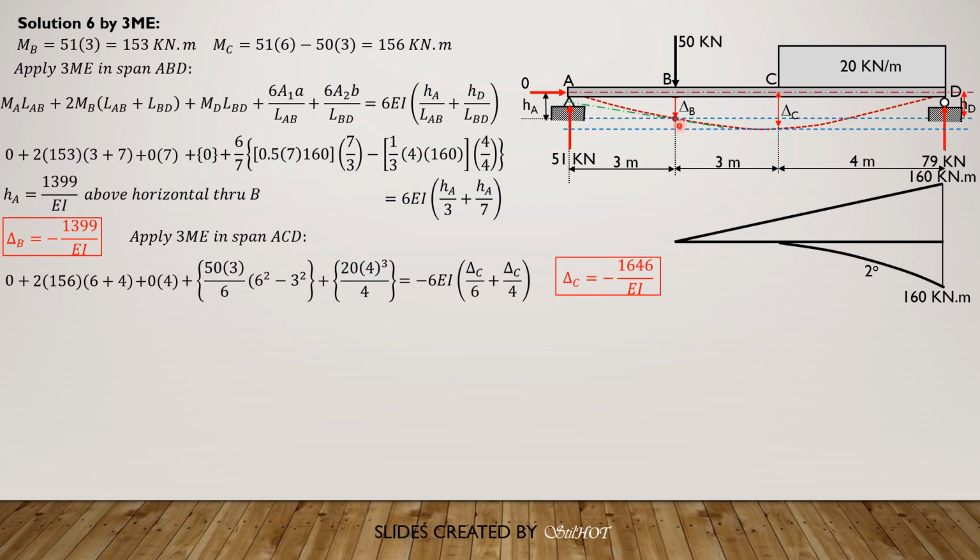Then if that is the case, the distance of point A from this reference tangent is the deviation of A relative to the tangent at B. And because this is the tangent at B, the angle that the tangent makes with the horizontal is the slope of B. So if this is true, then theta B is negative because the tangent is rotating clockwise from the horizontal, right? So theta B is negative.